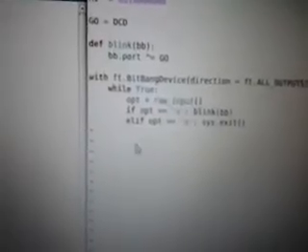Then here we go, we've got this method blink, and what that says is it's going to change the current going through the port, and as we determined before, the port is going to be equal to the FTDI pin DCD. In here, we're using the BitBang device, which is just a mode that you can put the FTDI chip in, and we're setting up a loop.